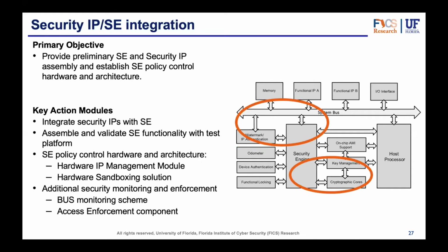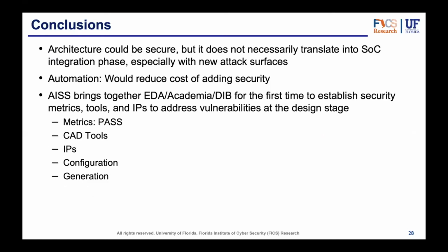Another one also focuses on security IPs that are being developed and how you integrate them with the SE, and then within all the IPs that we have in the SoC, it focuses on providing sandboxing solutions to the IPs, firewall concepts that Brandon mentioned earlier, and a hardware IP management module. Again, all with enforcement and monitoring capability for security properties, again, with a PASS metric in mind.